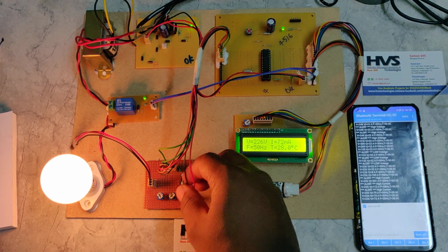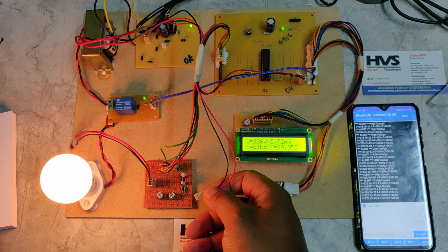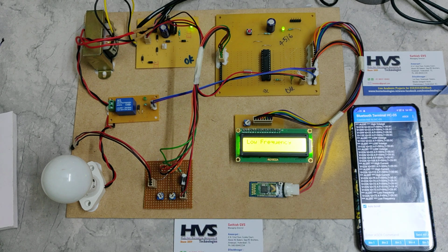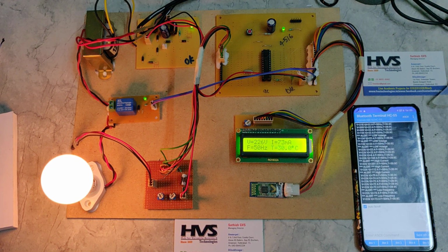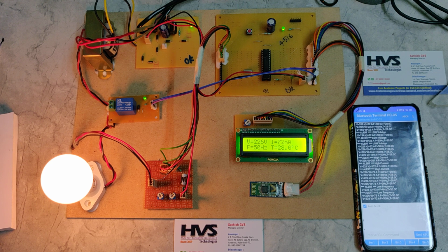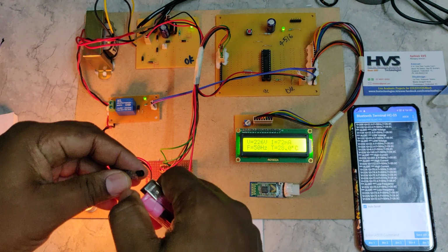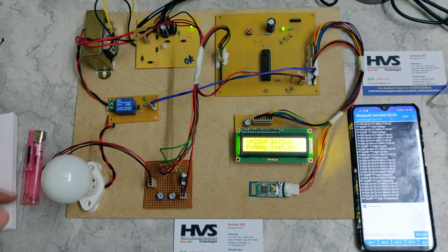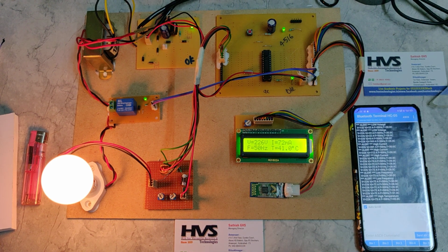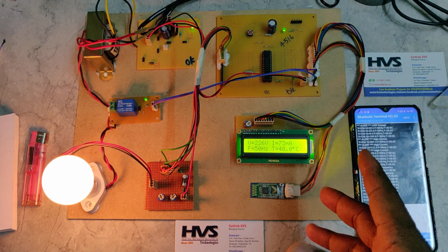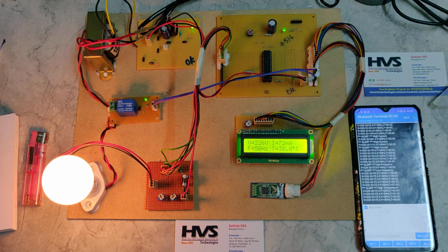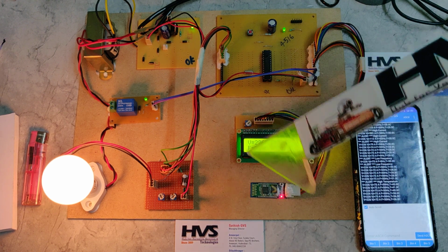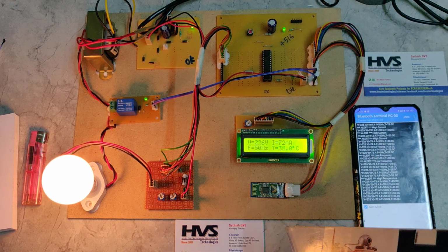Coming to making a fault over frequency, just unplug this. We can see the frequency is 0, and then automatically the load will be disconnected, low frequency. And the next is temperature, so high temperature. For every one of these abnormal conditions, we are going to control the device, and whenever it is a normal condition, we are going to establish the connection back to the load.